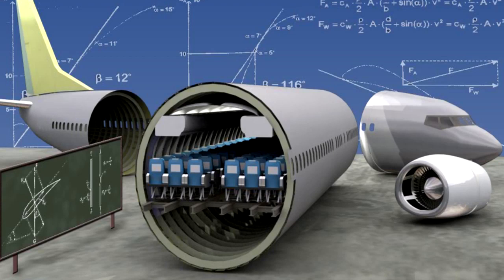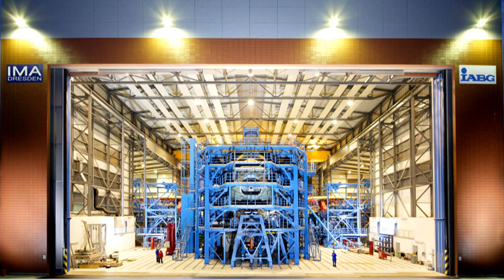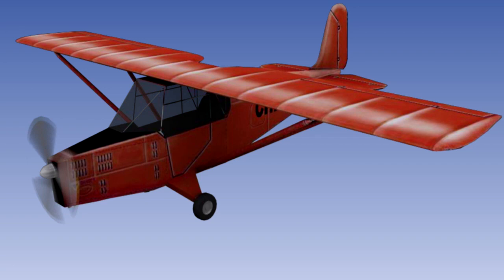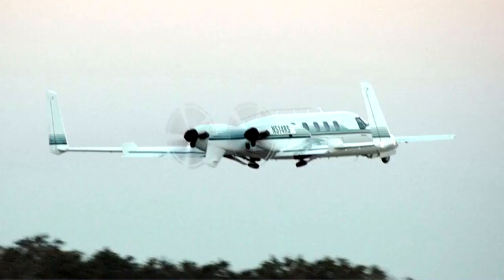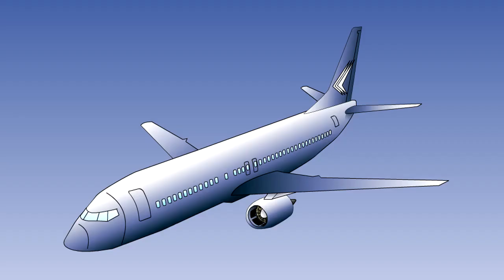In this lesson, we will discuss the construction of aircraft's fuselage, wings, and tailplane. There are three main types of fuselage construction in use. First, there is the truss or framework type, which is generally used for light, non-pressurized aircraft. Then there is monocoque, which is only rarely used. And finally, semi-monocoque, which is in use on most other types of aircraft. The last two types of structure are more generally referred to as stressed skin.